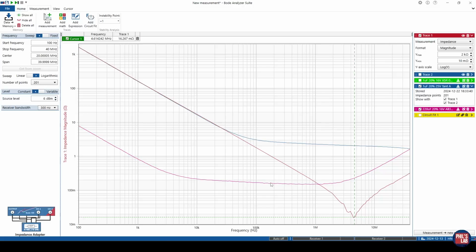Whereas the electrolytic capacitor, okay, maybe a slightly unfair comparison because it has a 220 times larger capacitance than the other two capacitors, but it also has a fairly flat broadband ESR range and overall fairly respectable impedance given the package size. However, the package size and the composition itself is a limiting factor, so we only get down to about 150 milliohms of impedance. So again, quite different than our 10 milliohm or 50 milliohm multilayer ceramic capacitor. So this is just to hint at that we do need to choose the right type of capacitor for the right application. Even within the class of capacitor, there are many, many differences, and that's why we need to model them and measure them.